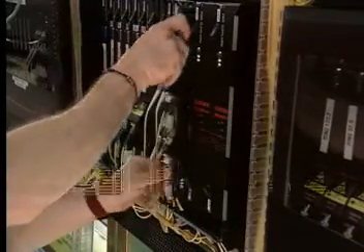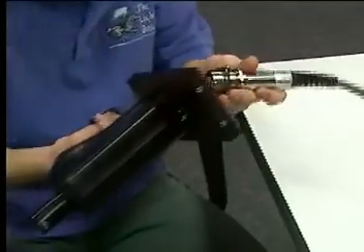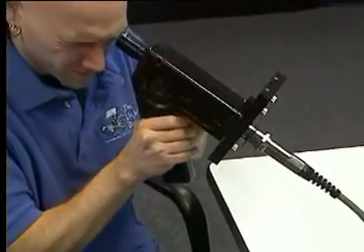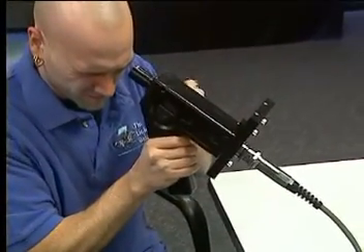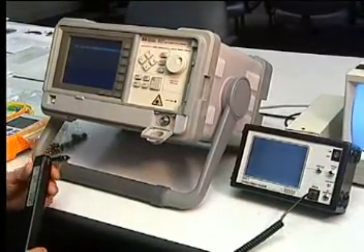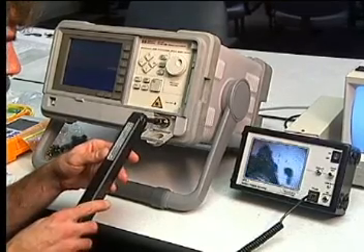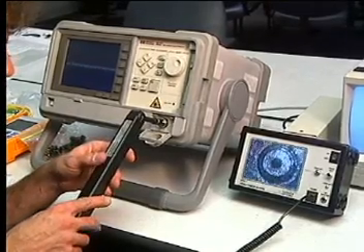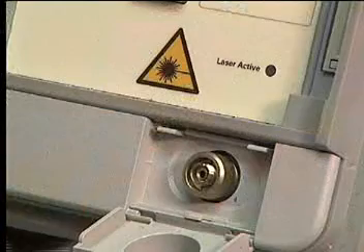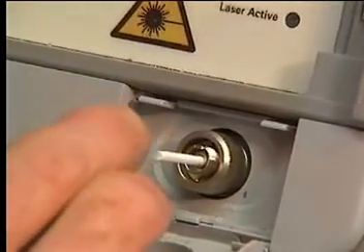dirt accumulated during shipment. This inspection scope is customized for aerospace connectors and features an XY positioning feature to allow inspection of individual pins or sockets in these multi-pin connectors. The connectors on test equipment such as OTDRs, optical spectrum analyzers, and other high-performance instruments require 100% inspection and verification every time the instrument is used. It is critical that the connections on these instruments remain clean and undamaged.